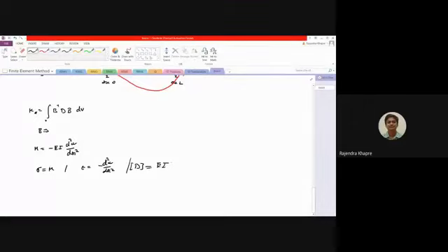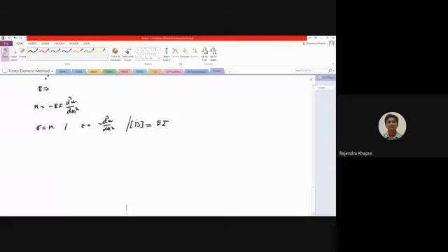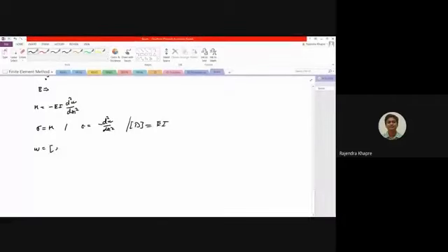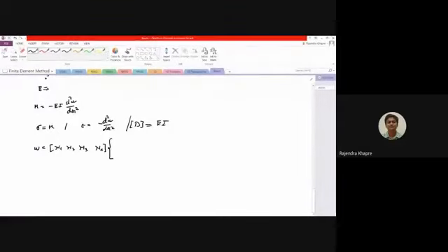Okay, so now coming back to the original derivation part, we have already seen the value of W. W was nothing but N1, N2, N3 and N4 multiplied by W1, theta 1, W2 and theta 2. Just now we have seen this. This is the variation of the displacement. Now all I have to do is go for the strain.